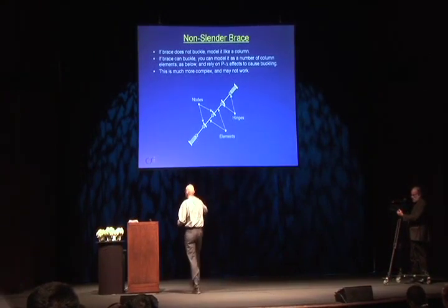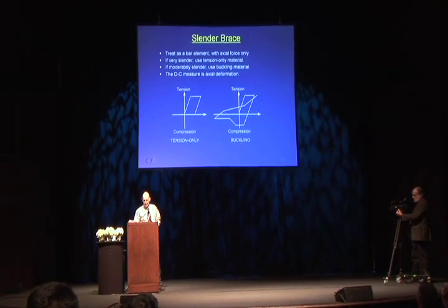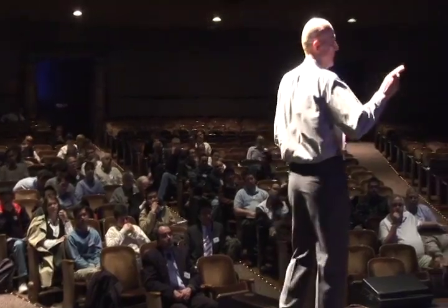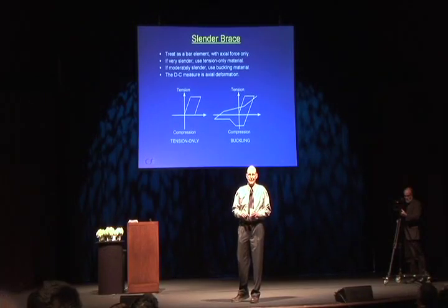But if you have PM interaction with a lot of bending stiffness, but it still buckles, you could just treat it as an axial member like this. And if you wanted some bending stiffness and some axial buckling, maybe you could put two members in parallel. One could be a column with plastic hinges but no axial stiffness, in parallel with something which has axial stiffness and no bending stiffness, and maybe you could fudge it a little bit. But if you really want to model a braced frame or a column that actually buckles, that's a tough problem, and I'm not sure exactly how to do it.